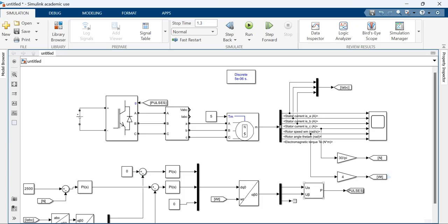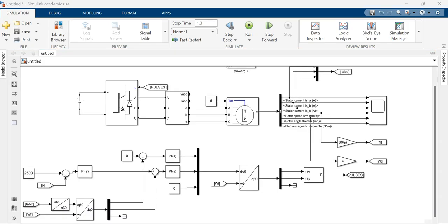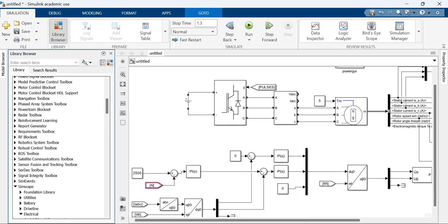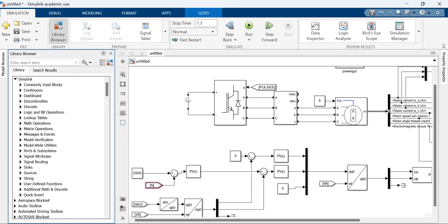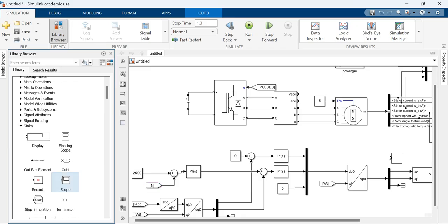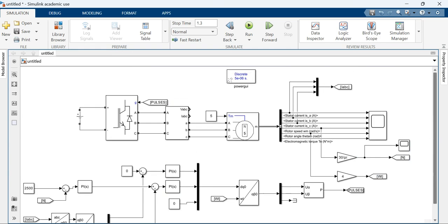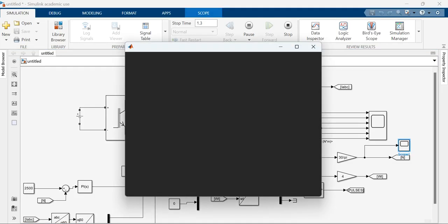And this is what all about creating the Simulink diagram. So let me put a scope to view the speed at this point n. So let me have a scope here, which is again taken from Simulink Sinks scope. Let me drag it and put it on the screen. And this is what I'm interested to look. And now let me run the simulation, and let us wait for the simulation to run.